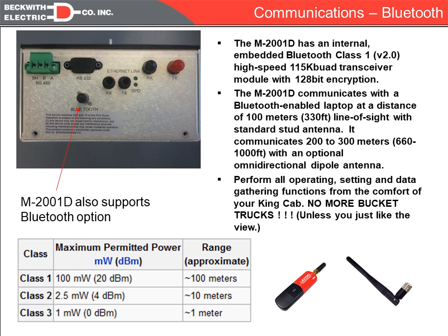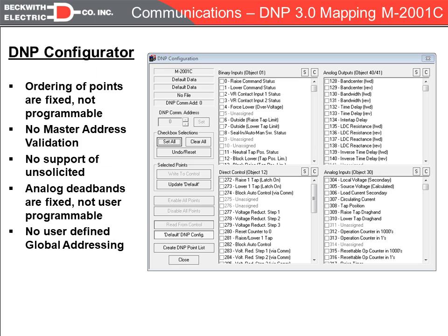If it's a line regulator and the regulator controls are hung 20 feet up, and normally you would need a bucket truck to access them, these are all areas where the Bluetooth can provide benefit. The Bluetooth can communicate via either Modbus or DNP. It is encrypted, so it does have security and pairing, and you can hide the pairing.